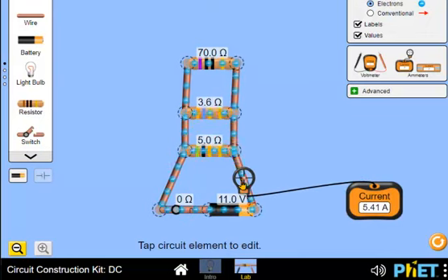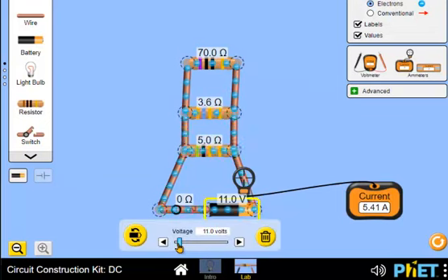Okay, so what I'm going to try here is aim for getting 1 amp, and then I can use Ohm's law again to determine the equivalent resistance. So I'm going to drive the battery voltage down till I get to about 1 amp. Okay, getting close. Whoa, okay, there we go. Oh, I'm really close. Okay, so I have 2 volts divided by basically 1 amp, which is 2 ohms, but because I shifted the decimal point here, it's actually 20 ohms, which of course was the answer we had on the calculator, 20.3 ohms. So it still checks out.